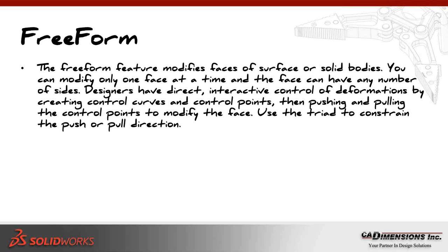Now, the first one, I'm covering kind of the best first. I think Freeform is one of those tools that could be utilized a lot more in the software if we just knew where it fits. The Freeform feature works on faces of a solid or surfaces. It allows you to modify the face interactively with push-pull control, and it allows me to very precisely control the direction that I'm pushing and pulling, the location on the surface I'm pushing and pulling, and if I have symmetry. All of those things play a role.